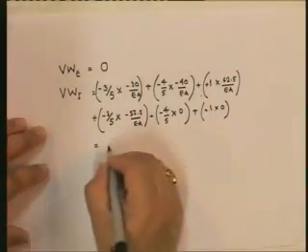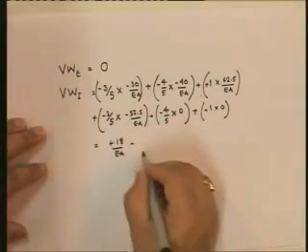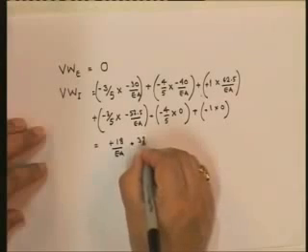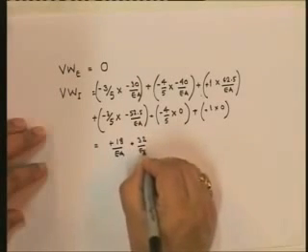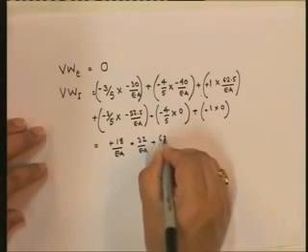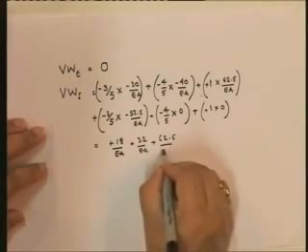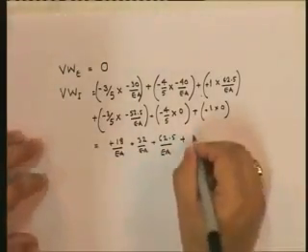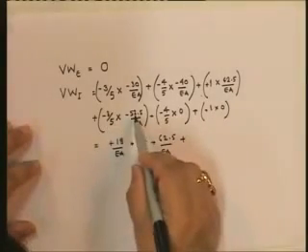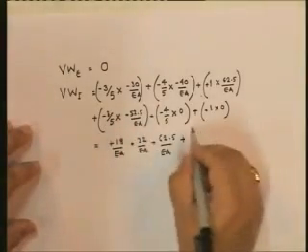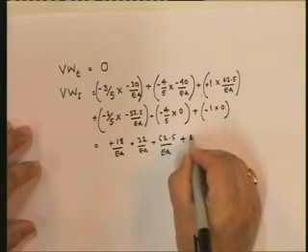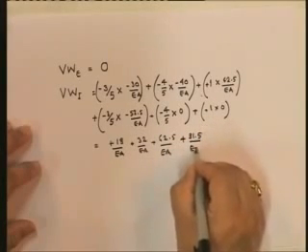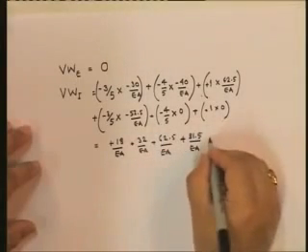So what is the total internal virtual work? You will see that it is going to be equal to plus 18 upon EA plus 32 upon EA plus 62.5 upon EA plus 10.5 into 3, which is 31.5 upon EA, and these are 0 and 0.